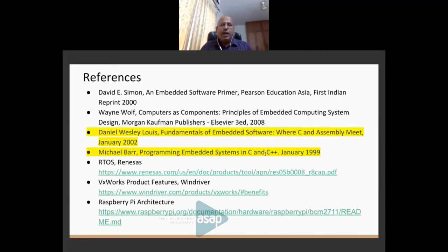But even during execution of the application, you can change the priority of a task at runtime, basically to avoid things like priority inversion. But the designer, as part of designing the application, understands which tasks need to have high priority, and then in the configuration of the operating system in the beginning, you will set up the priority number for different tasks.